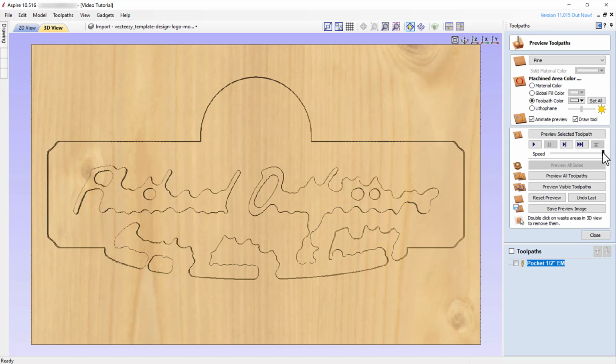It is very important to review each toolpath to be certain that the result we obtain is what we originally intended. Sometimes we can overlook something, and if we don't check the toolpaths beforehand, we will not be happy with the result when we go to carve our project.